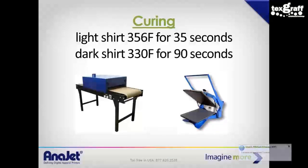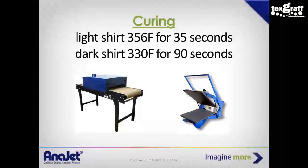And if you ever have a slight concern that you're not doing it for the correct amount of time, because temperature can fluctuate with these heat presses and tunnel dryers, increase the temperature by 5 degrees and increase the time by 5 seconds. So instead of going 356 for 35 seconds, go to 361 for 40. Or instead of going 330 for 90 seconds, go to 335 for 95. That way you'll ensure that the garment is getting cured adequately and is going to withstand the wash.